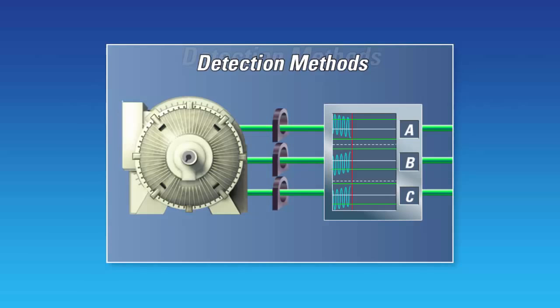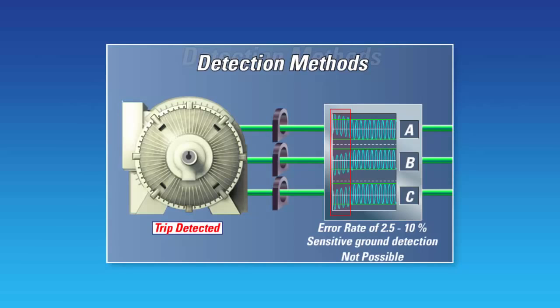During the motor start, the motor's phase currents typically rise to magnitudes in excess of 6 times the motor's full load current. The slight mismatch of the differential CTs, combined with the relatively large phase current magnitudes, produce a false differential current which will be seen by the relay. This current will be misinterpreted by the relay as a ground fault unless the ground fault element's pickup is set high enough to disregard this error.